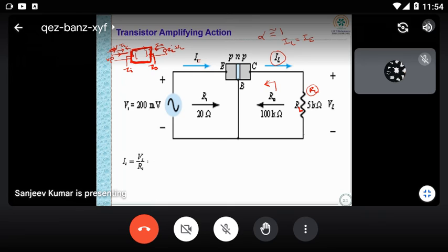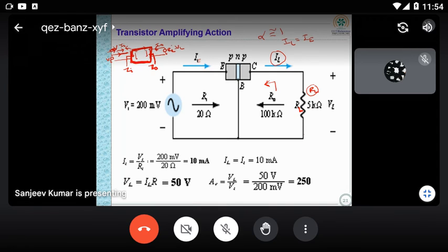But we cannot take that impedance value because this is of your device, and across that load you are measuring the voltage. So in this question, your RL is given as 5 kilo ohm. That's why you are calculating the voltage across RL only. To get that voltage, I have to find out how much current is drawn. The current drawn is equal to 10 milliampere, and then you are calculating the voltage. Clear? Yes, sir. See, the load resistance you can vary, so you can take 6 kilo ohm, 10 kilo ohm, it is up to you. But in this question it is 5 kilo ohm. I hope every part is clear.